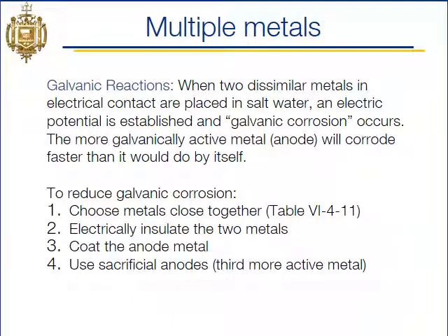All right, so multiple metals. If you get multiple metals put close together, you can get what's called a galvanic reaction. And what essentially happens is the atoms from one metal will be pulled off, and it'll cause corrosion from one metal, and they'll sort of attach to the other metal.